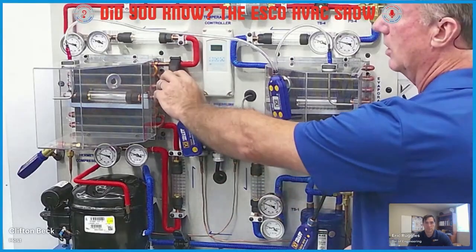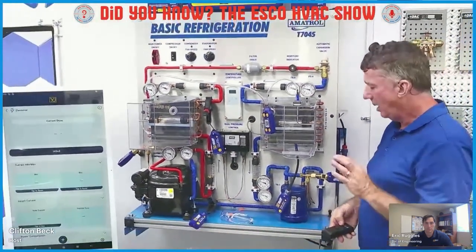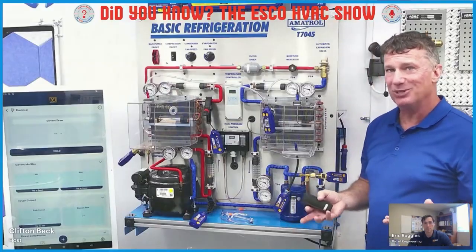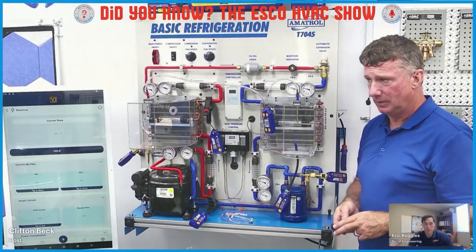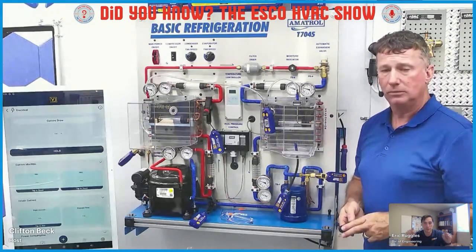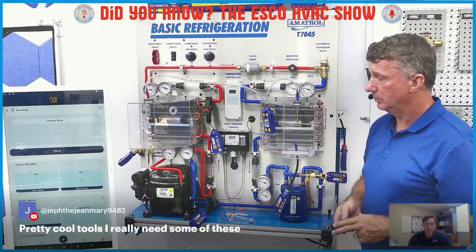That way all of our tools are the same color. Because I've noticed too, Eric, with all of your instrumentation, they come with red and blue indicators for each tool so that you can mark which one is going to be used consistently on the low side or low pressure of each connection. Yeah. Obviously, you can switch them on the app pretty quickly, and we can show you how to do that. But if you're in a heat pump system, you don't have to physically remove and change the locations like you do with other ones. You can just switch them on the app and change what's reading. So then, when you go to heating mode or whatever, you can just switch the sensor locations on the app.